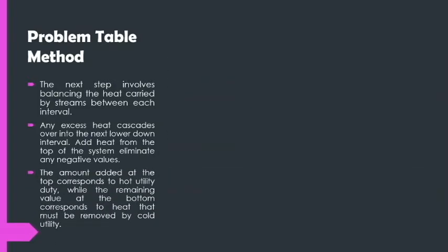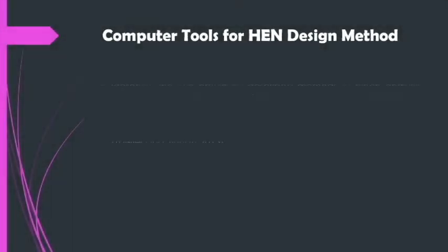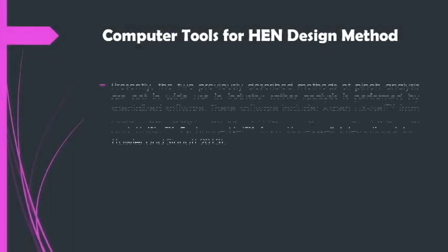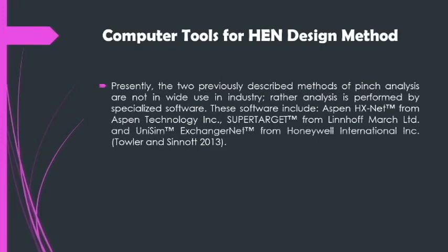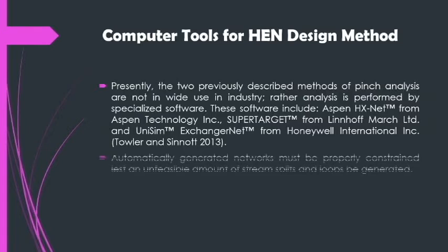So the last one is the software method, which uses computer tools instead of the hand design method. Presently, the two previously described methods of pinch analysis are not in wide use in industry, where the analysis is performed by specialized software such as ASPEN HX-Net, SuperTarget, and UniSim ExchangerNet. The automatically generated network must be properly constrained, lest an unfeasible amount of stream splits and loops be generated.